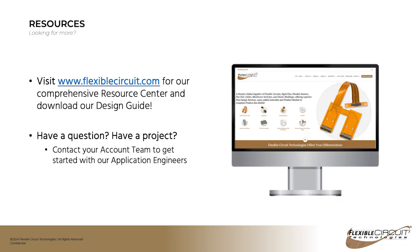One thing that we do on a regular basis, if you have SMT components, and it's very difficult for us to make rectangular and square access openings in polyimide cover material, so what we'll do is we use a combination. In the areas where we have your SMT, we'll use solder masks because those areas aren't bending. And the remainder of the circuit, we'll use polyimide covers so that you can go ahead and bend them and get the tightest bend ratio or bend radius that you need there. So that's something you can discuss with us, and we do that all the time. And it's a great hybrid that gives you the best of both worlds.